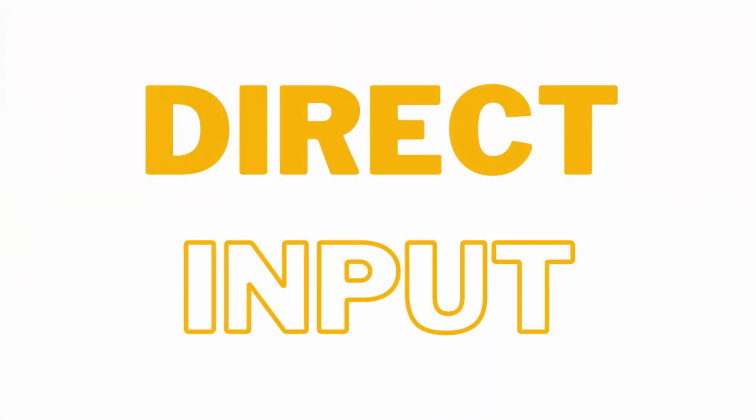Alright, let's start by taking a look at the direct input method. There are 2 parameters that need inputs to work with this method: LS luminous length and LS IES basis length. The IES basis length is simply the length that's been assigned to your IES file. LS luminous length, however, is the length that you'd like to stretch your linear to. Now, let's go hear from Kyle and see how you can do it in Revit.